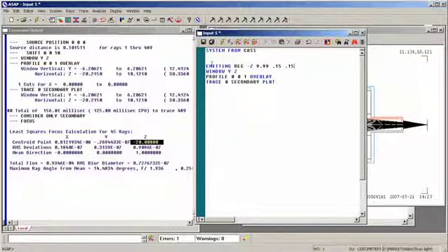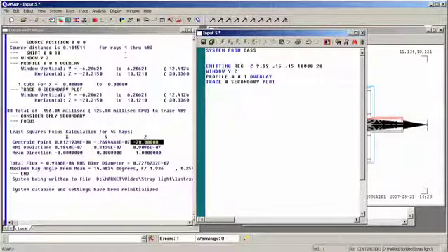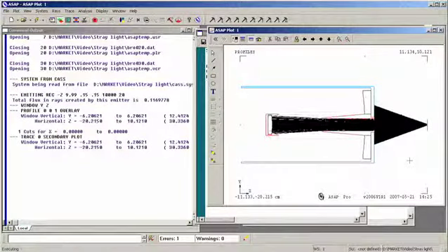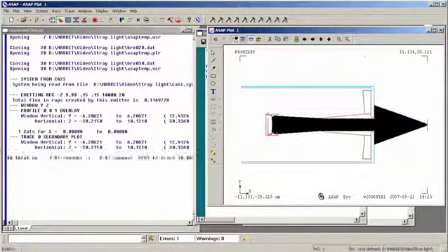That is to say, the detector dimensions are 0.15 by 0.15. Same thing. And we have to tell it how many rays to trace. We'll say 10,000. And we're going to confine those rays to a 20-degree angle just to make the ray trace more efficient. We issue the end command telling ASAP I'm done with my previous work, and go ahead and execute this file. Here's our backward ray trace.